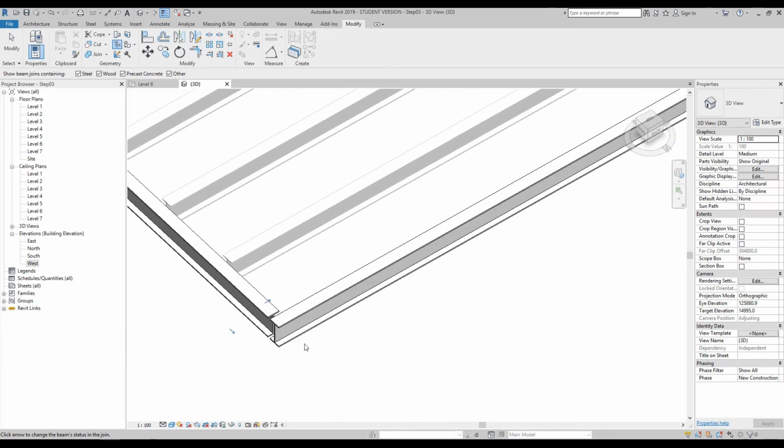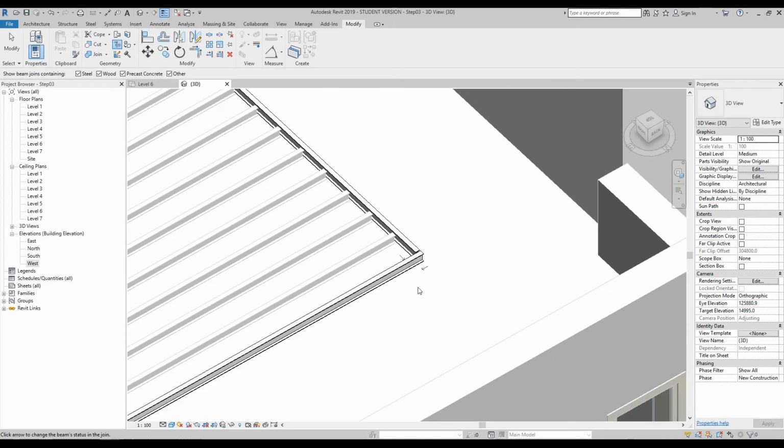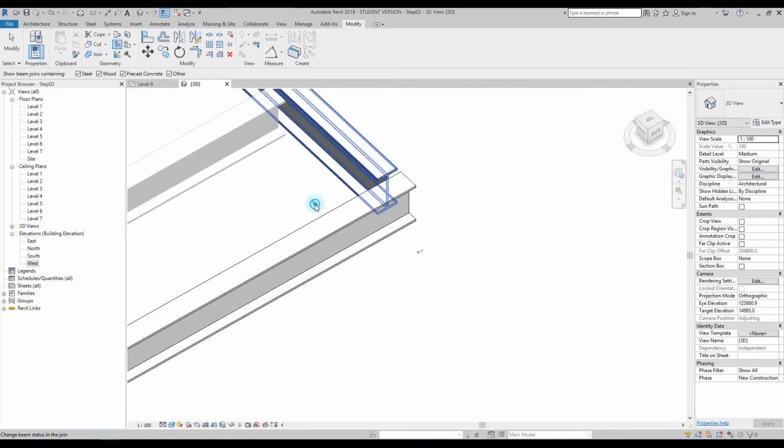What we're wanting to do is click this little blue arrow here, and you'll see that it's disjointed. Now if you repress it, it will join, but then there's another one where you press it here and it will actually do a 45-degree joint. Once you do that, you'll notice a little lock symbol. Once you hover over it and it goes gold, click it once to lock it. We'll do exactly the same on the other side. Hover over the lock till it's gold and click once.